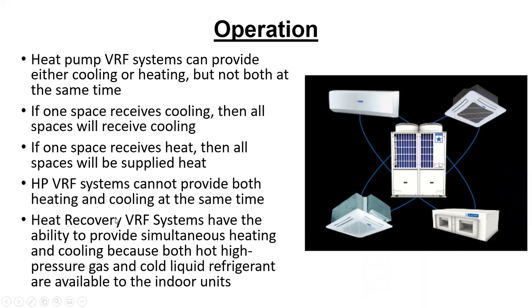Heat recovery VRF systems have the ability to provide simultaneous heating and cooling because both hot, high pressure gas and cold liquid refrigerant are available to the indoor units. So if you want to be able to simultaneously heat and cool, guess what? You've got to go with the heat recovery system, which of course is going to cost a little bit more.